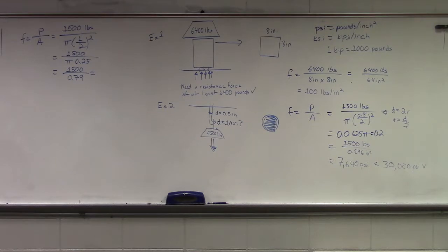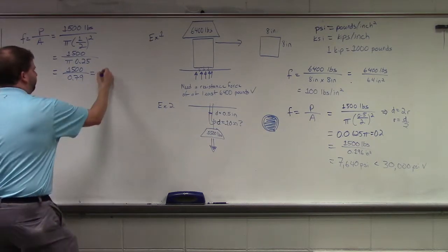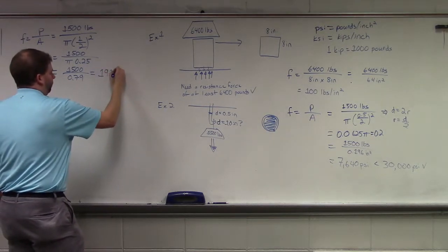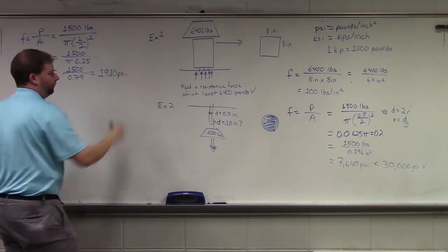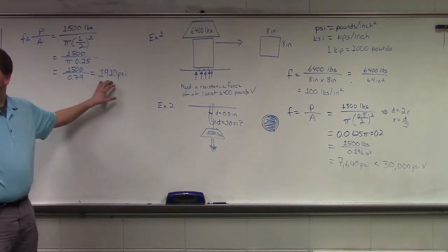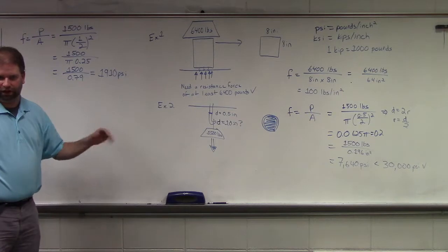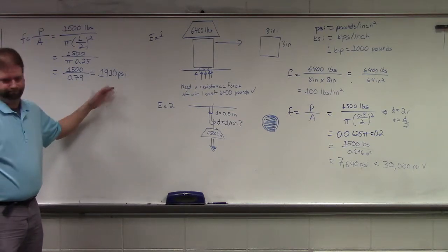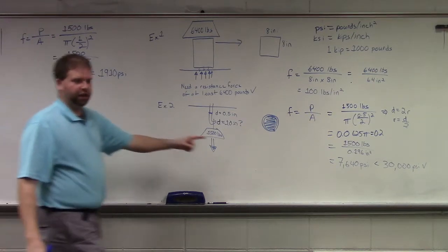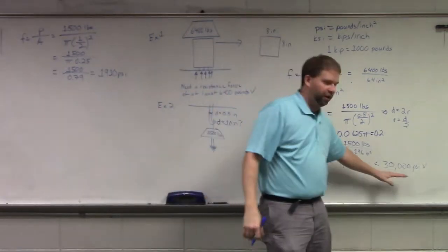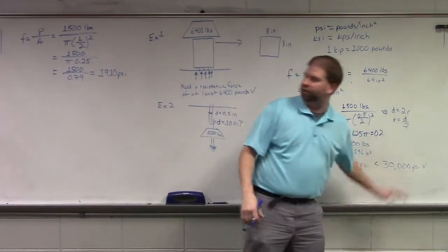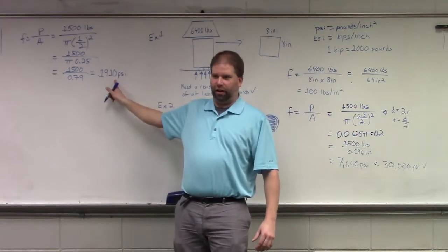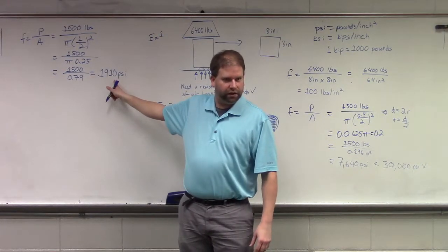Roughly 1,898 PSI, versus 1,910. In the grand scheme of things, with an allowable stress of 30,000 PSI, does my cable care all that much about 1,898 versus 1,910?